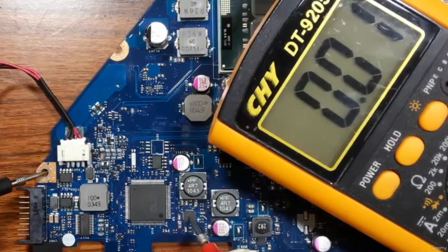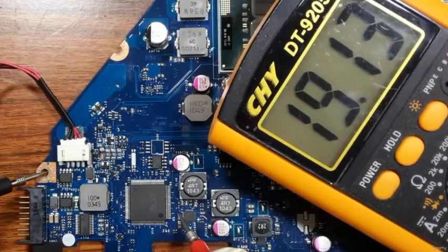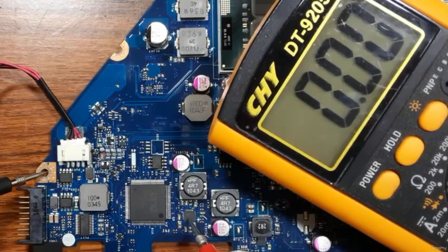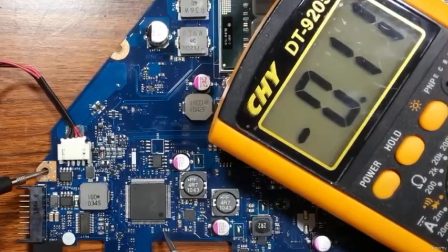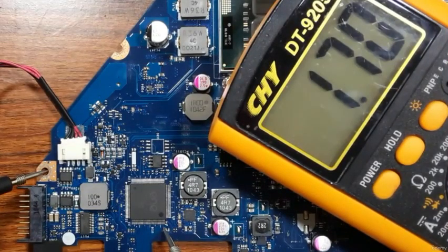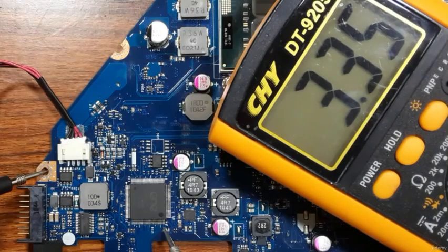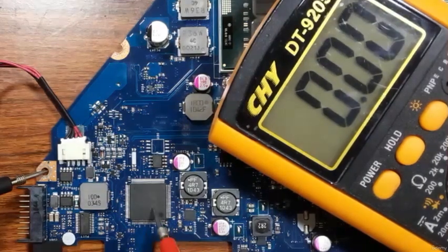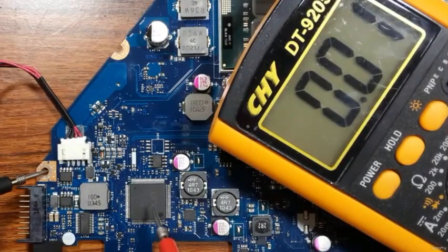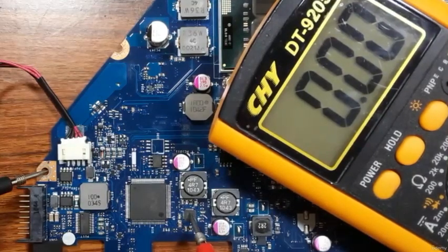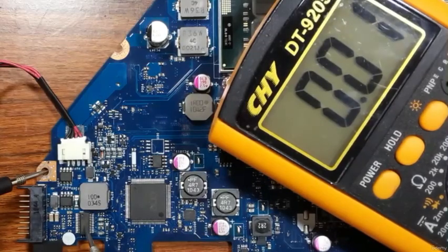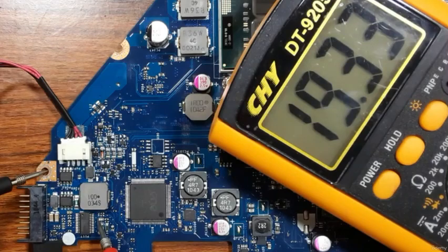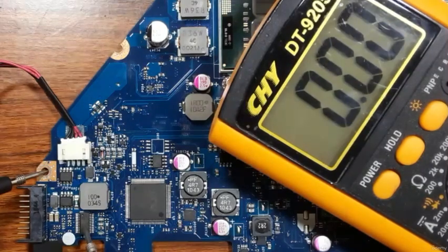So this is an IC. This 19 volt is the working power for this IC, the power management IC. So let's check this capacitor here. As you see, I have here 3.3 volt, because the 3.3 volt is the working power for this. For every power management IC, for example, let's check this. We should find here 19 volt. As you can see, we have 19 volt because this is the power management IC.